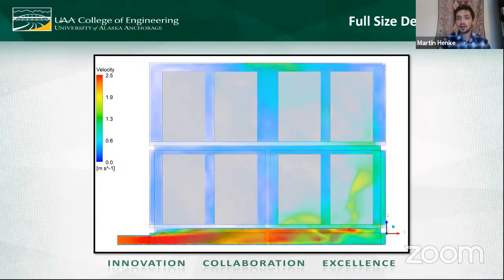So going into the full-size model, there again is that same default design, the Vortex generator design, and then the vented model design. Here we're seeing the default model design. That same air is ported in through the bottom, it comes through, and it doesn't diffuse, unfortunately, until it hits near the rear of the case, and then comes back up and is ported out. So obviously, it's experiencing many of the same problems that the experimental default model experienced, where batteries towards the front are not adequately receiving airflow and thus become very hot.